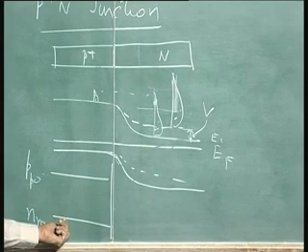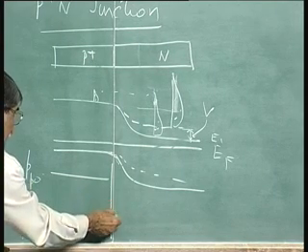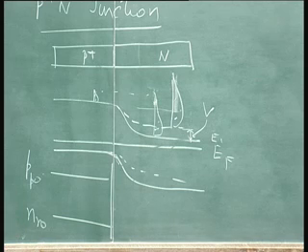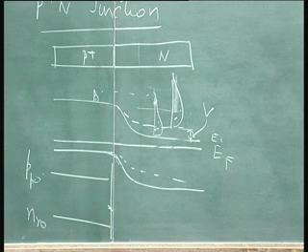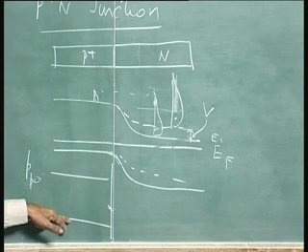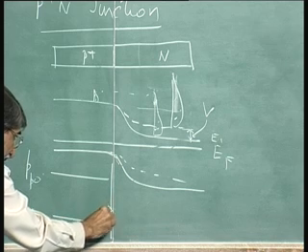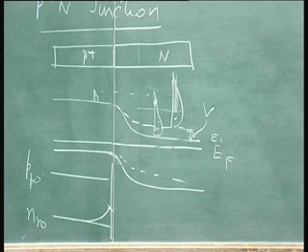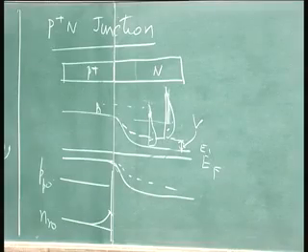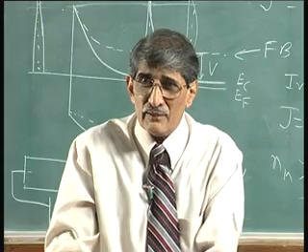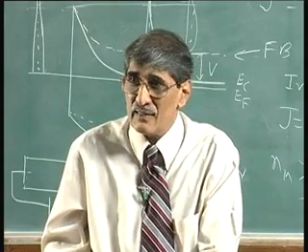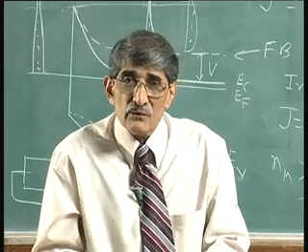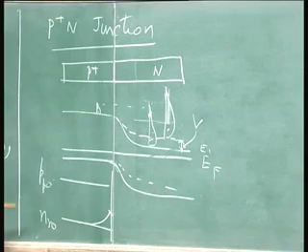So, immediately when you inject at a fast rate, what happens? You are dumping electrons at a fast rate from the boundary. Therefore, that concentration goes up there and there is no concentration there. So, from that point onwards it is carried away by a very familiar sight now. The concentration builds up there because it is not being taken away fast. It is not being taken away fast because it is a minority carrier and it would need a very large field to take it away. There is no field there, large field. Small fields are not sufficient. So, carriers get piled up there, that is why this builds up here.